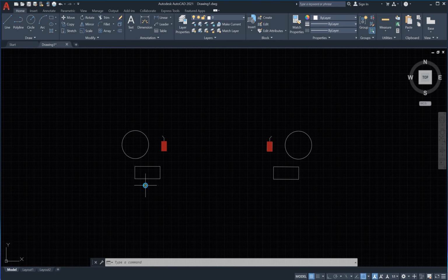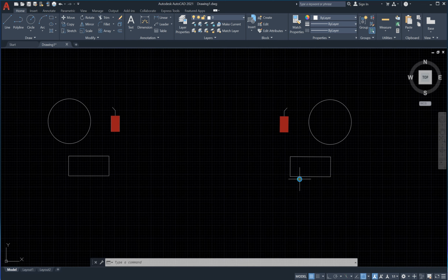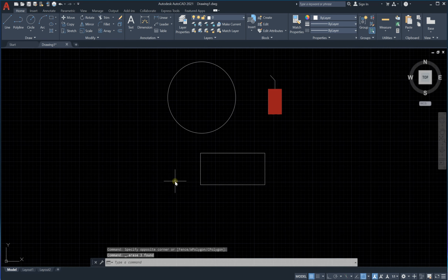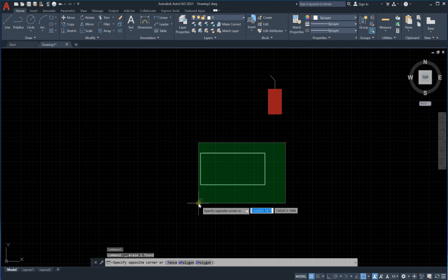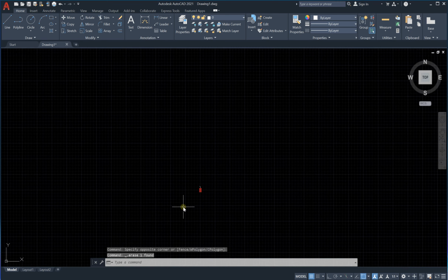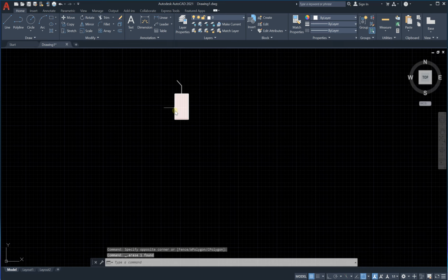So we learned till now about the insert command and the other command, which is mirror. Great. Now we would like also to learn about another one which is helpful. Okay, what is it? Let's just delete this and delete this. This command is called scale.